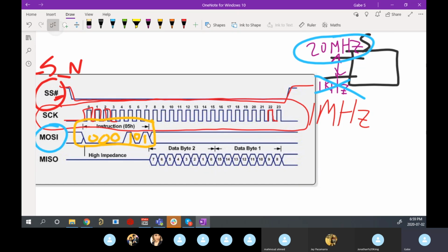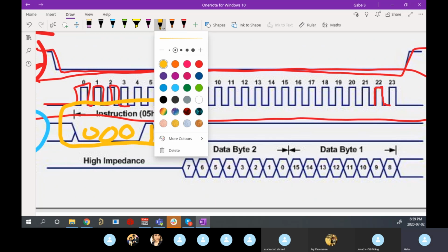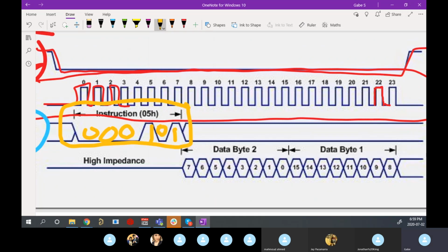And the way you know to sort of split those up is by how fast your clock is going. So one period of the clock would be 1 bit of data. So you'd have 1 bit of data here. And then another period of the clock would be some other bit of data. And based on how fast your clock is going, these will grow wider or shrink smaller, basically the length of your ones and zeros. So your clock defines how fast they go.